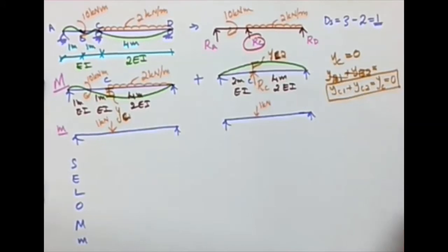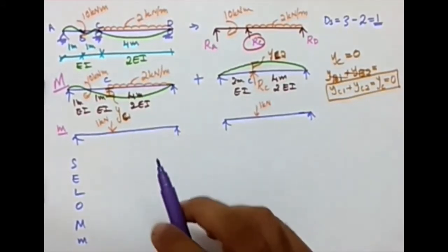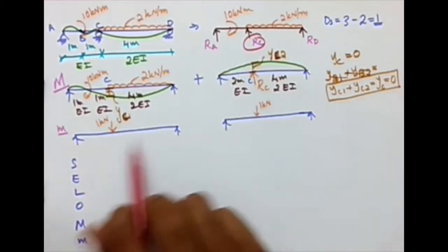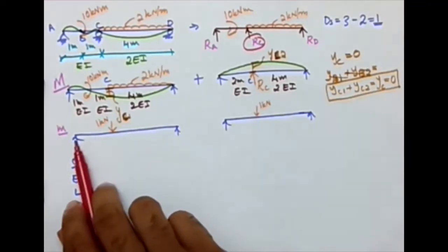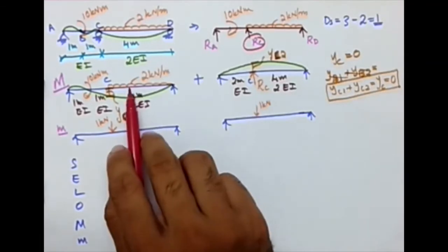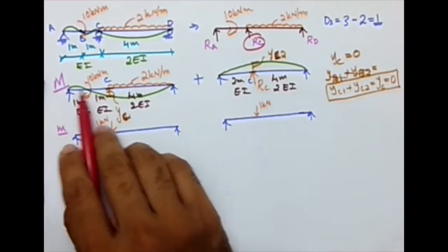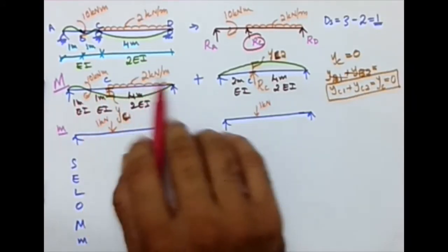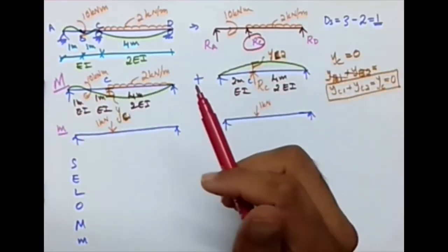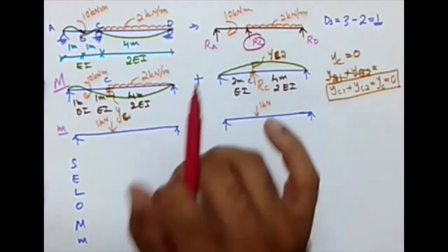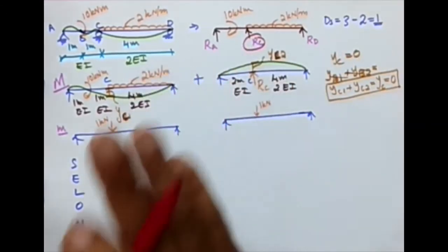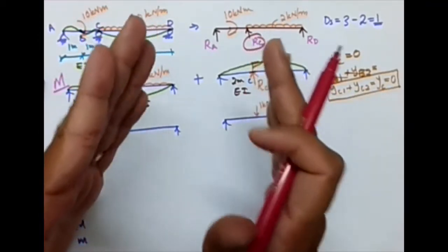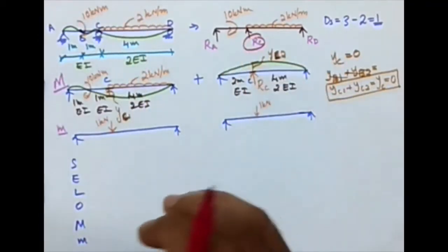Now, how many segments are needed? That's a point where we need to focus a bit more compared to the earlier problems. Here, if you are observing this, we need 2 segments, 3-point forces, 2 segments. But in the capital M figure, you can see there's 1 point here, 1 point here, and this is the location of another point load. So I may think about how many segments are required. Segments are basically considered by considering in a portion, if the expression for bending moment remains the same, that can be considered as a segment.